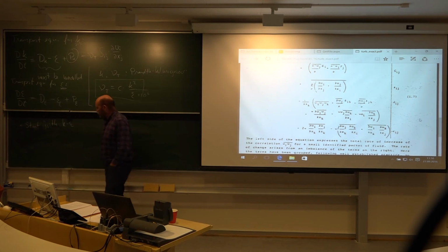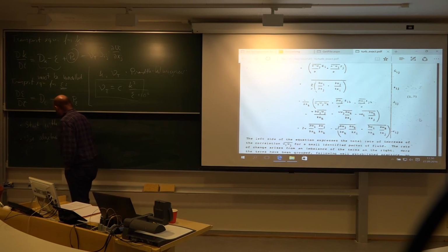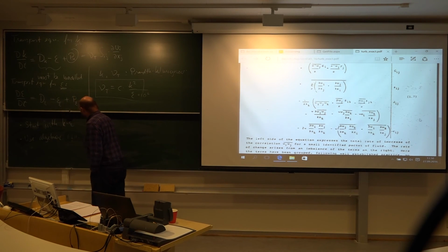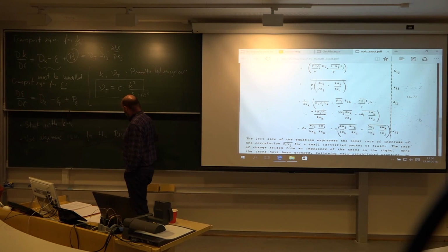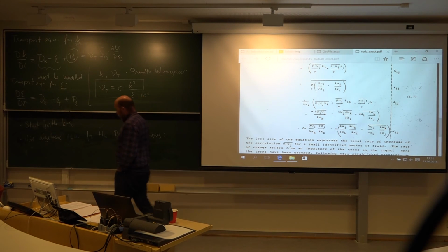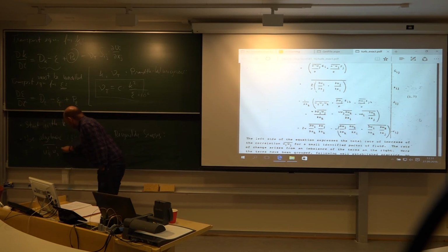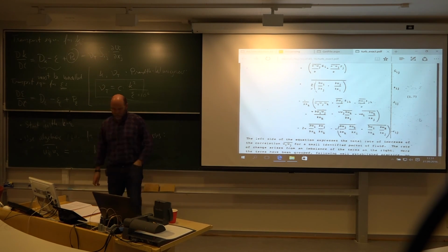Then you use algebraic equations for the Reynolds stresses. So then you will have an equation saying Ui, Uj, fluctuations time averaged equals, and then just algebraic equations involving K and epsilon.